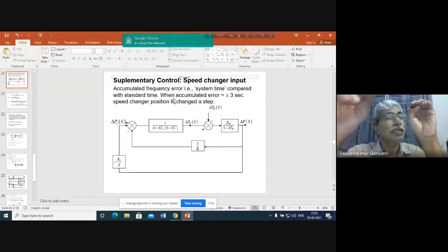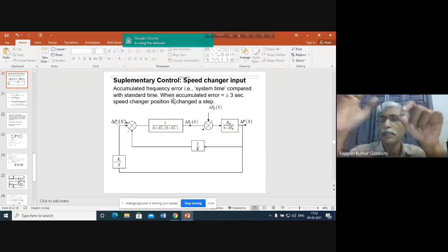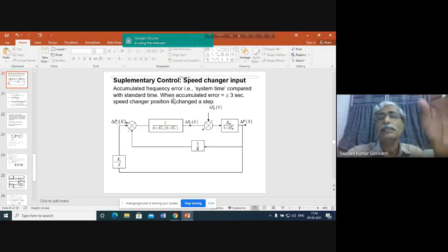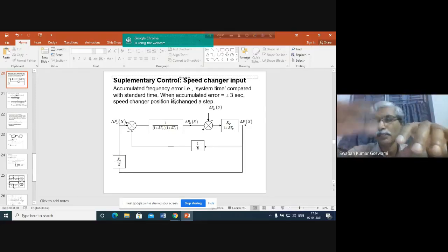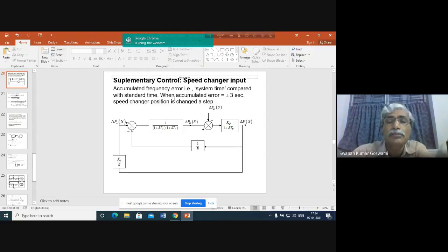That is because of the availability based tariff. You can say that the availability based tariff is also a part of frequency control of our system. Obviously, for final frequency control, for restoring the frequency back to the initial value, you have to depend upon the supplementary control. Otherwise, it cannot be done. But the excursion is much less. Why is it much less? Because there is no undeclared transaction of power. Previously there were undeclared transactions of power. That's why the frequency excursion was to a wide range.